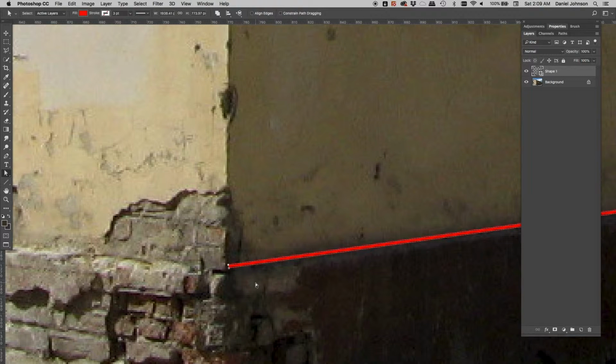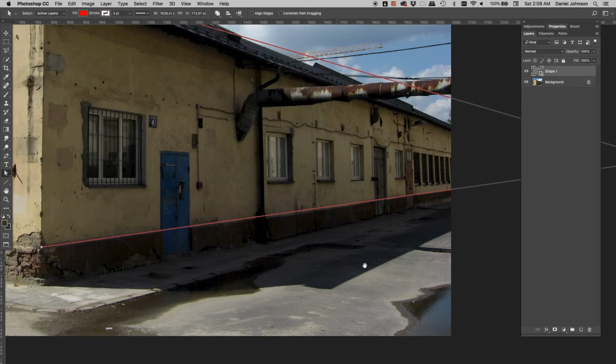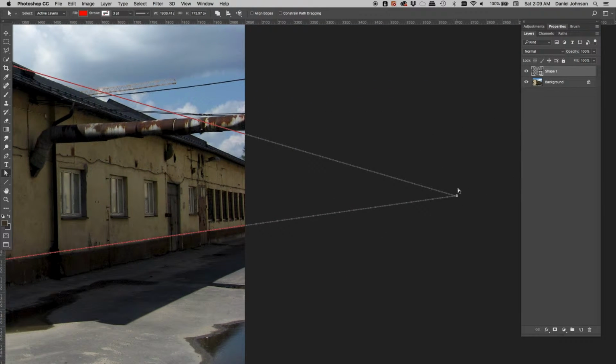This isn't a line segment tool like in Illustrator where you've got one point on each end. You actually have two points on each end because it's a long thin rectangle. So as I zoom out, I'll come over here, and this is where those two lines intersect. What that really means is that there are four points right here where they intersect. I want to make sure I grab all four of them, so to do that, just grab a little marquee around that. Now they're all four selected, and you can move these in and try to match up where those should go. So that should be about like that.